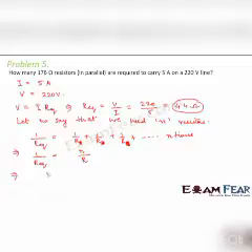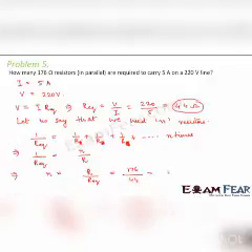Right? So from this we can say n is equal to R divided by R equivalent. What is R? R is the value of each resistance, which is 176 ohms, and R equivalent is 44 ohms. So this gives 4. So we need 4 resistances in parallel so that it can carry a current of 5 amperes on a 220 volts line.